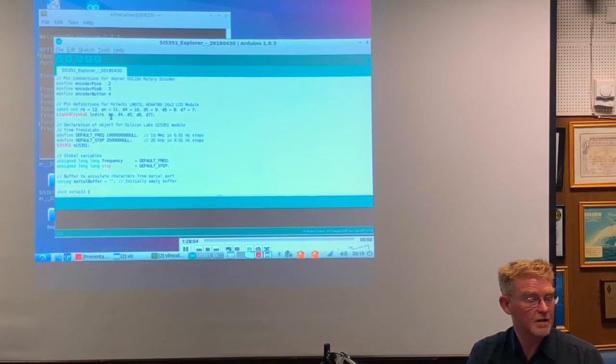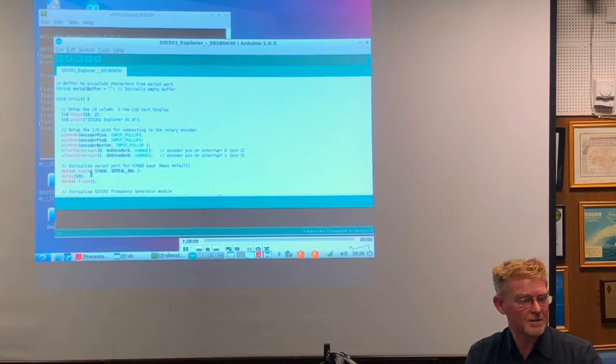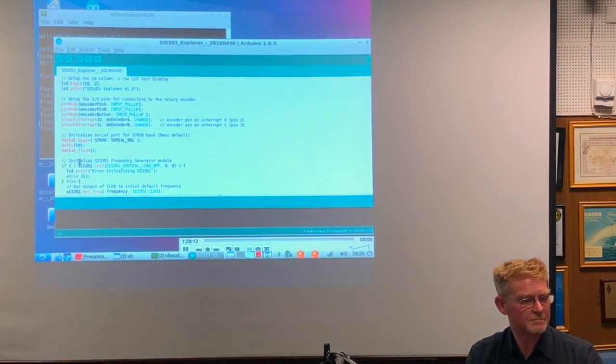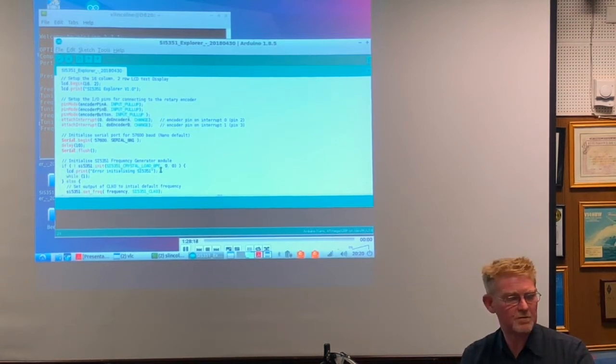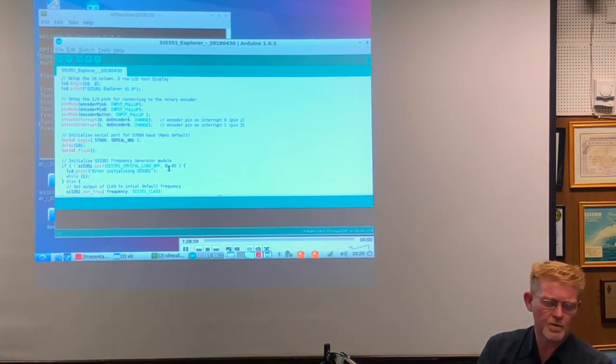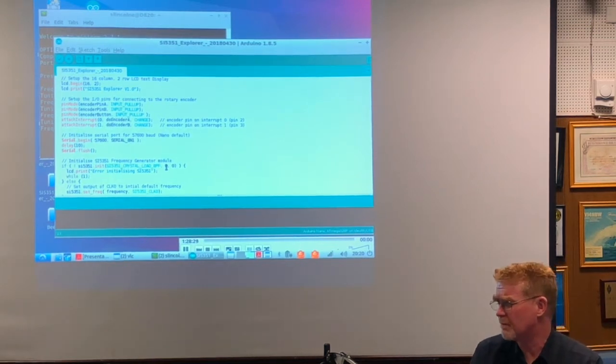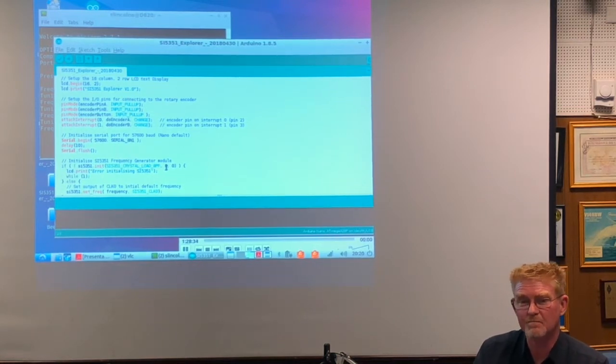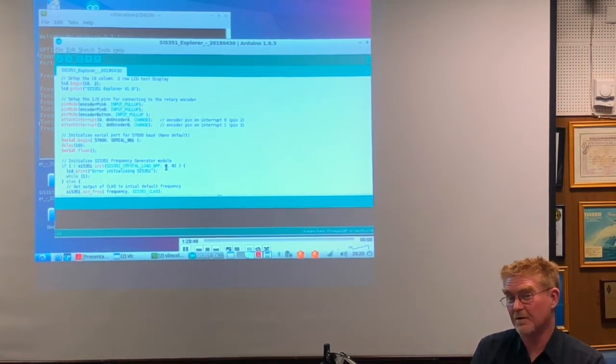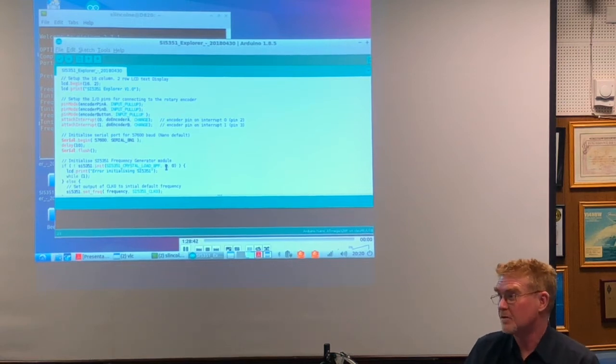So that's literally instantiate the variable, if we can say that. Then you tell it to go off and initialize itself. Here is where you tell it the load crystal on the oscillator module to use, and the other options I think were which output to use and the correction factor to apply to the clock. It's got a 25 megahertz crystal somewhere on that board. There's clearly no TCXO or anything really stable in that environment, so you can compare the output against a real-time source and say add or subtract so many hertz and get something closer to an accurate time.